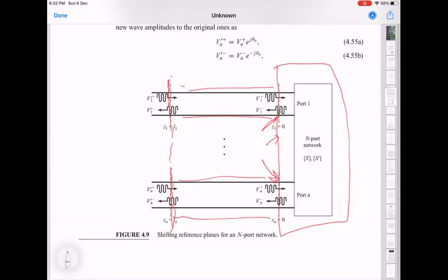But in most practical cases, this is not just a simple transmission line. It will have some loss. It might even have some frequency dependence. It could often have not perfect 50 ohms. There could be mismatches at the junctions itself. And these things make things very complicated. Now, having said that, if this intermediating object is really terrible in terms of all of these properties, that is, not really 50 ohm, too much frequency dependence and all of that stuff.